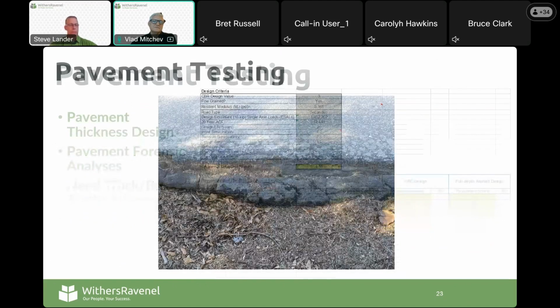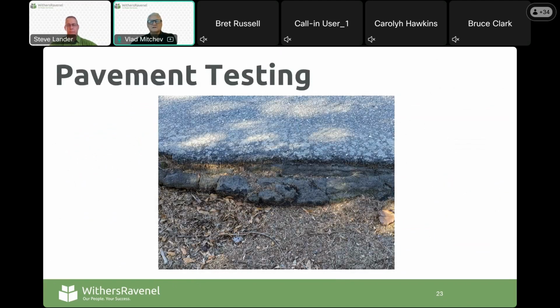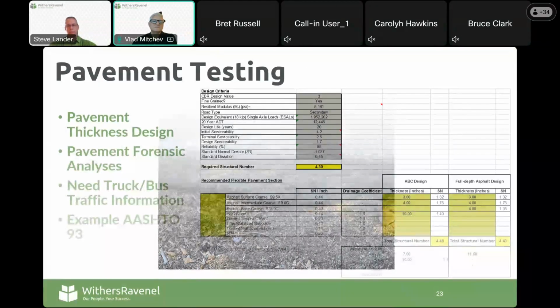So if you have 8 inches of FDR in the pavement design, and this is 5 inches of sand asphalt, your sample needs to consist of 5 inches of sand asphalt and the 3 inches underneath, whatever that is. In this case, it is subgrade. But if there is a base course, the proportions will be the base course and the subgrade, so that you can match these 8 inches of design FDR.